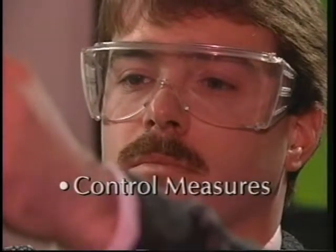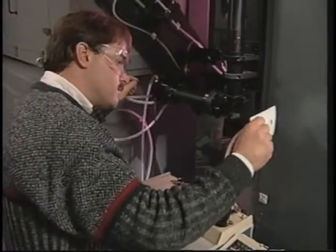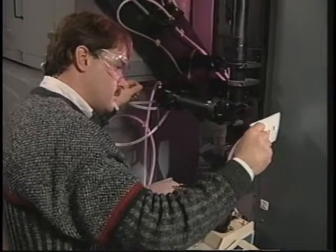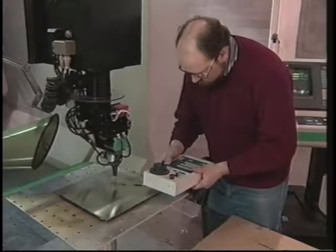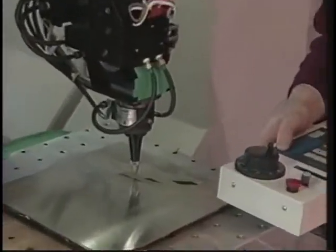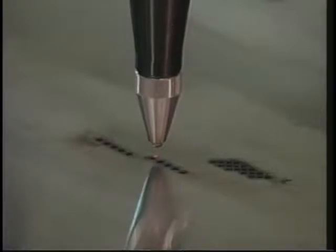If you have to work with an open beam, never directly view the beam. Use sensor cards that fluoresce or re-radiate the laser energy at a different wavelength from the beam. This allows you to safely view the beam through protective eyewear. When aligning open beams, reduce the power of the beam as low as practical. If at all possible, align a high-powered beam using a coaxial beam from a low-powered laser.